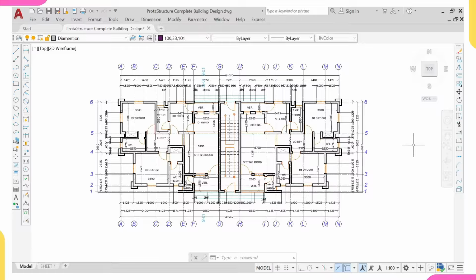Even if it's a residential building, you also check the residential building. Are we having any gym area? Because you know that if we have any gym area, the loading on that slab will be different, in the sense that gym equipments have high load, they are all heavy equipment, and two, they will be contributing higher load on the slab. So the gym slab will not have the same loading as the other slabs.